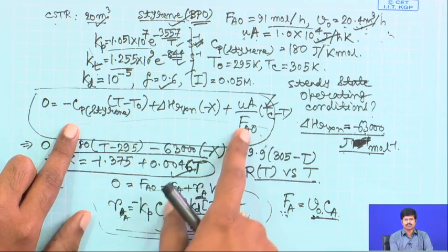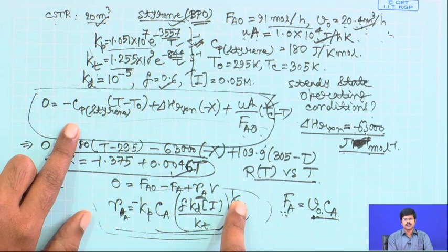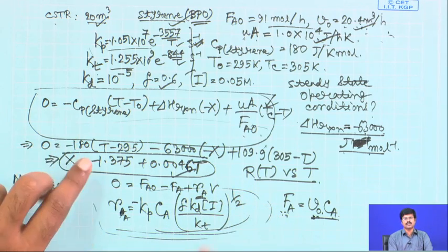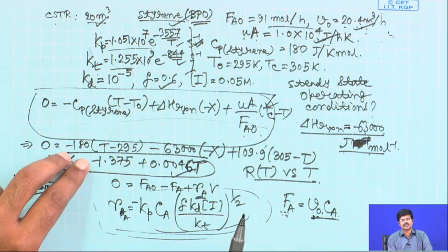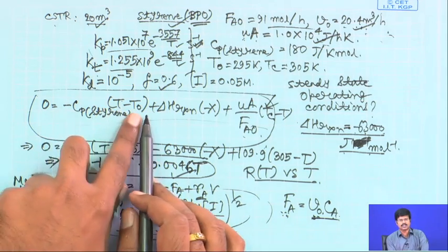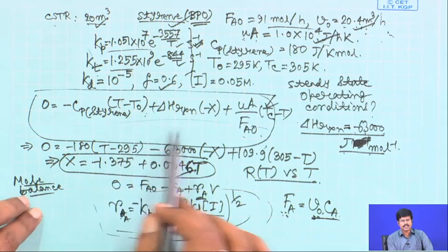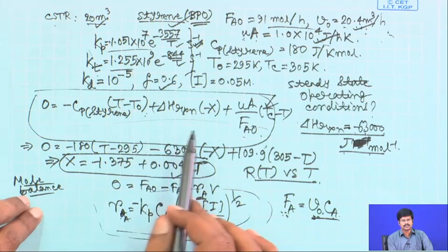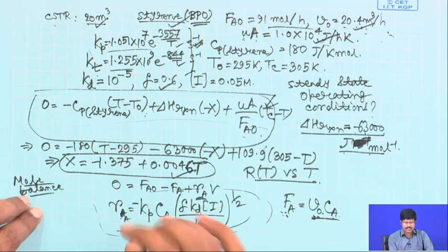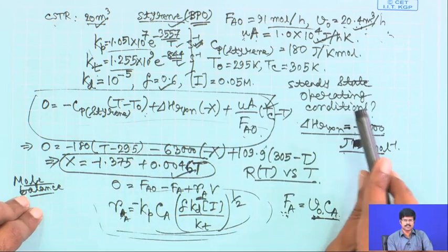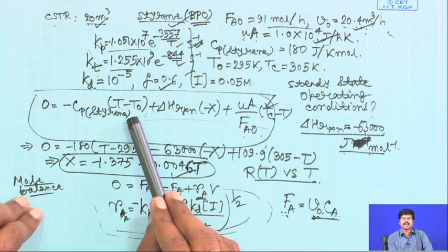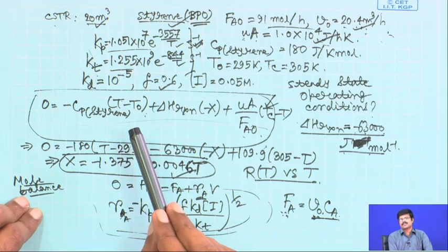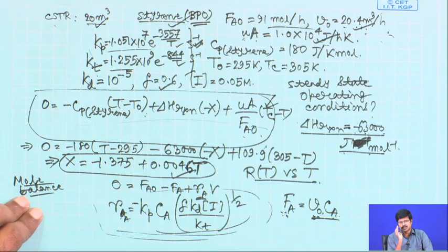The situation that we are working in, although we are keeping the temperature of the reaction mixture constant, strictly speaking is different from the typical isothermal situation that we talked about, because T is not equal to T0. So, you are operating in a non-isothermal condition, because if it were an isothermal situation, the temperature of the reaction mixture would not rise in the first place with respect to the inlet temperature.